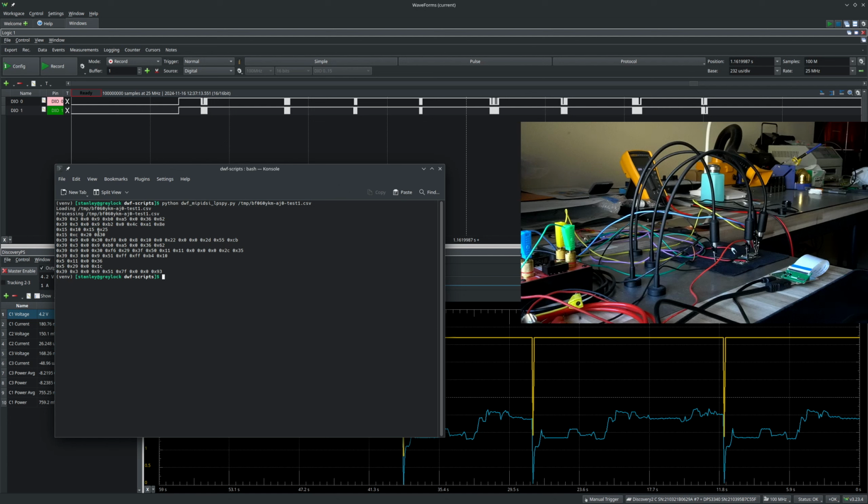So I did find some mistakes, like I incorrectly interpreted this data from the original reverse engineering run, so I have to fix that. These are not right. This at the end is coming from the backlight system. There's some additional backlight code I left in there in my Linux driver, which I'm probably going to remove for the time being to make sure this isn't causing any issues.